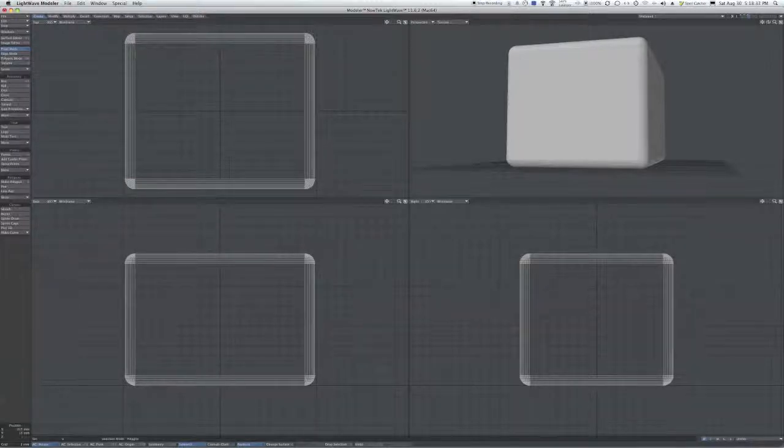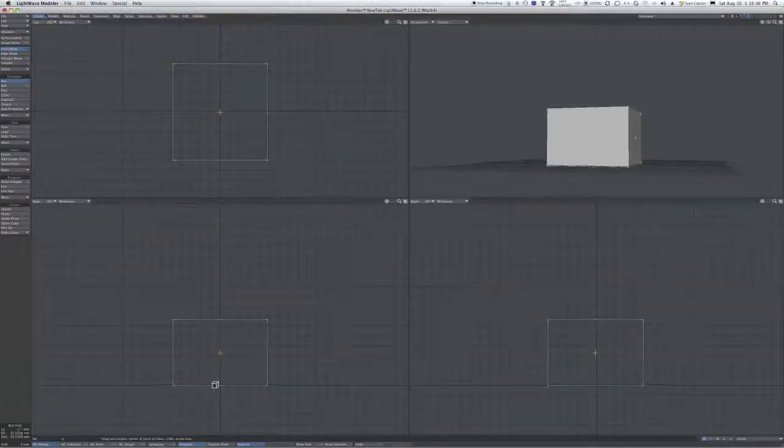Okay. Next thing. Let's assume that you have a problem with your print sticking. The corners always come up. Of course, you can print with a brim. You can print with a raft, things like that. You'll learn what those are later. But one of the things you can do to help attach a corner a little bit better is you can put something like this, a little disc, and I put that too far out.